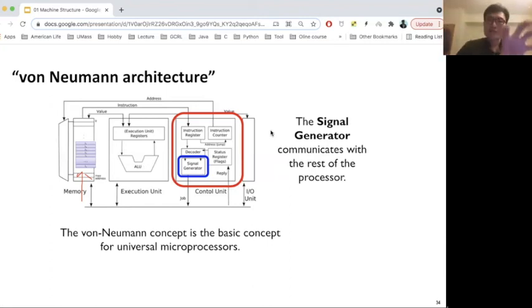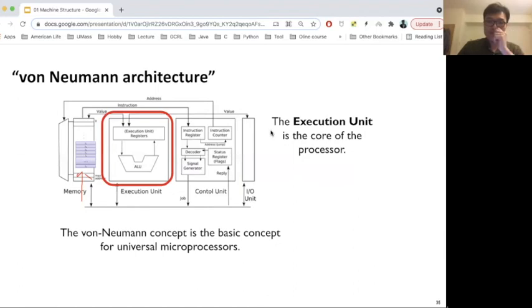So this is a part of your control unit. The control unit interprets the instructions, remembers the next instruction, and based on the current instruction does something. It's like a manager, like a commander, commanding every different piece in your system to do something for your new instructions. And the execution unit is very important because every computation, every execution is actually run here.